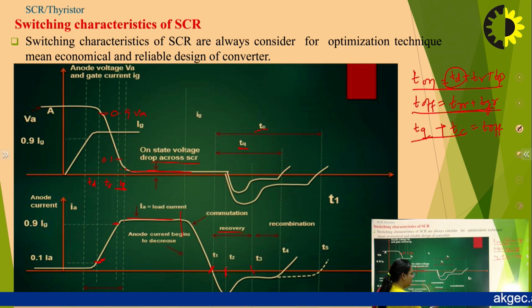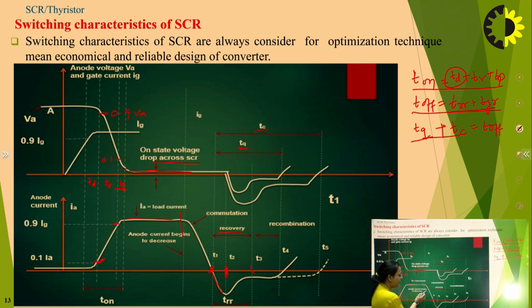At T2, about 60% of the excess charge carriers are removed from the outer 2 layers, right? After T1, you can see the anode current IT builds in the reverse direction with the same slope as that before T1. Okay.